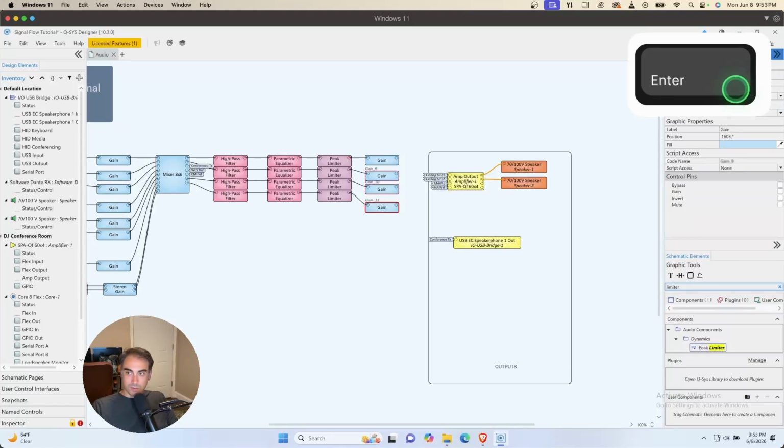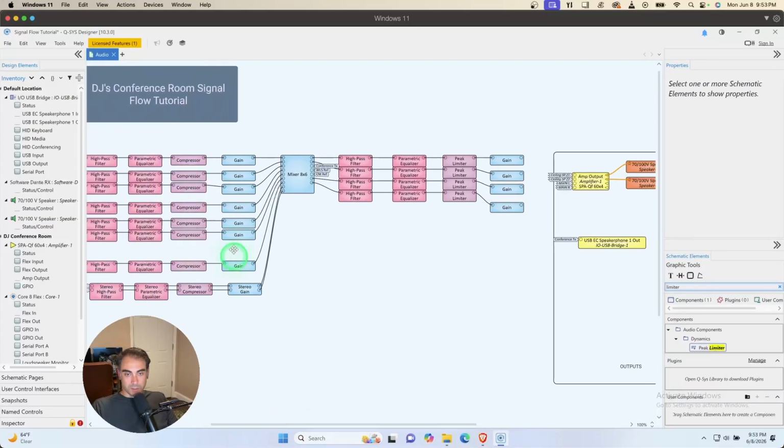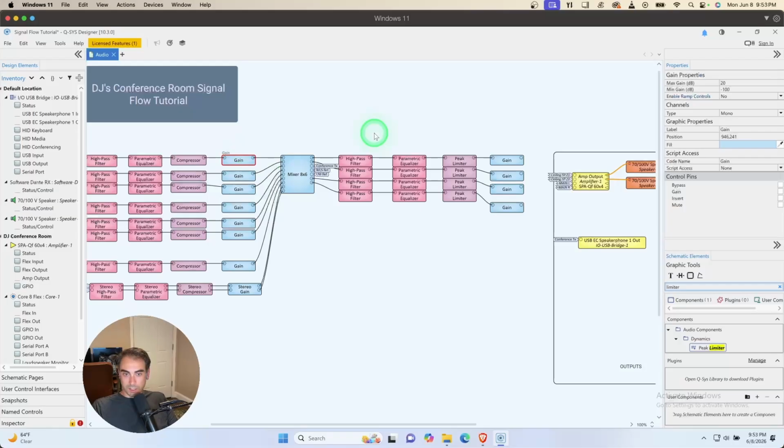This is really just, for me, a controlled volume, like something that would be controlled by the customer, something like this, a microphone. I like +3 to -9. They really don't need, really -6. 9 dB of gain, that should be plenty. You can go down the line and set those.